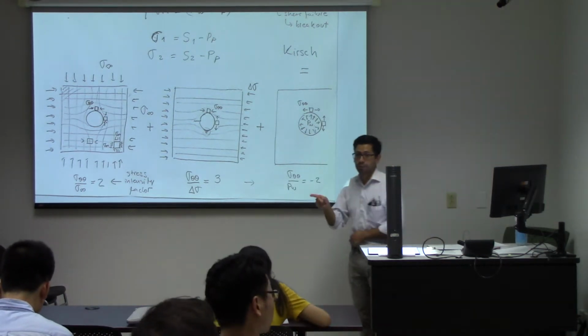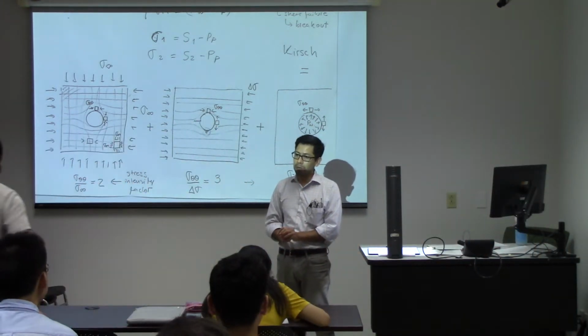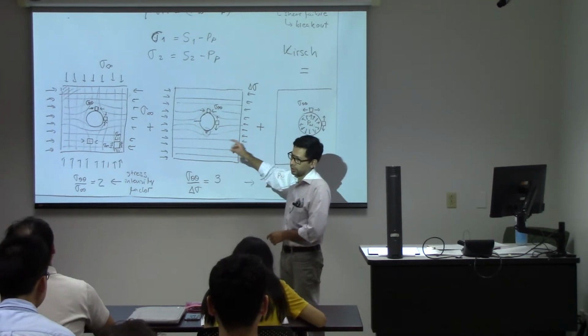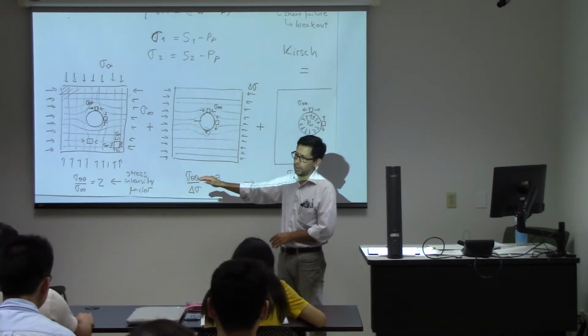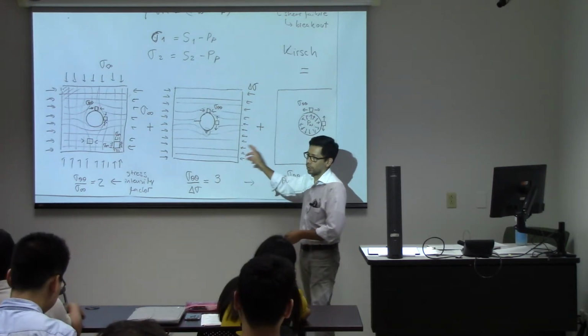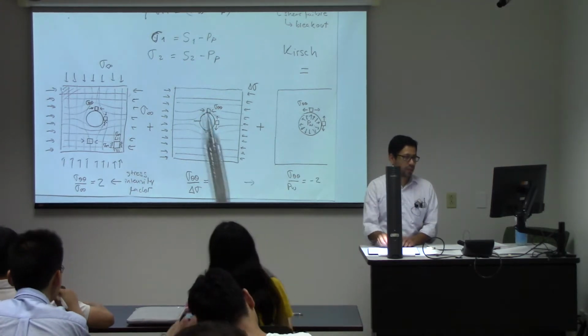And you should be careful with that too, with your finite element solution, because if you put your boundaries too close, you will not get the analytical solution to match your solution. You need to place them far away so there is no influence of the boundaries on the stresses around the cavity.